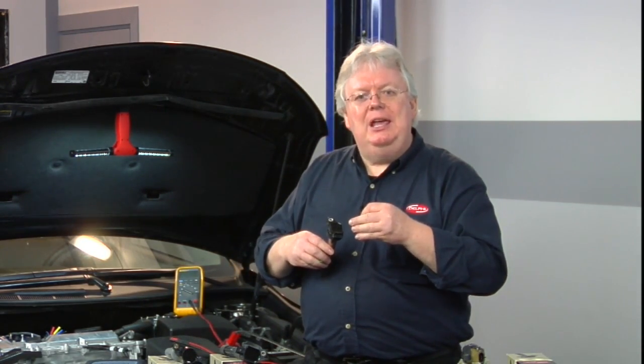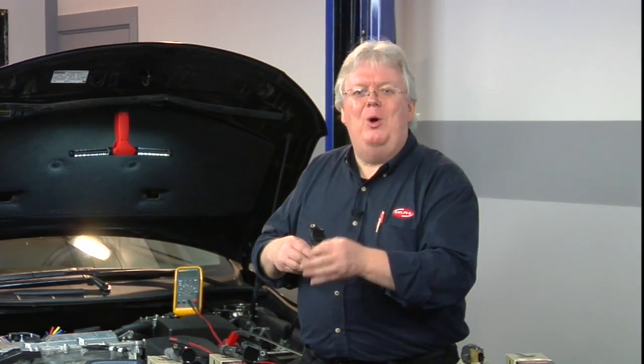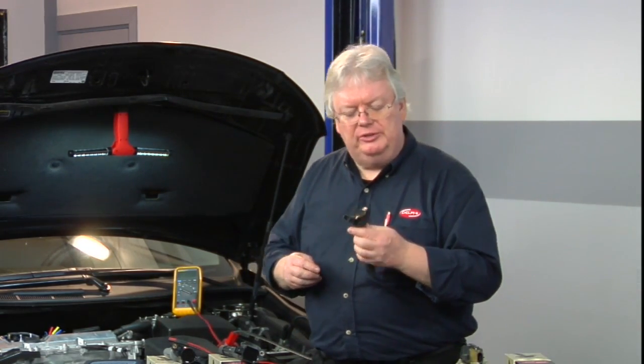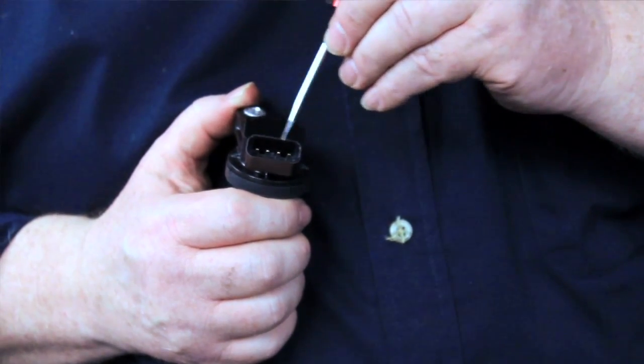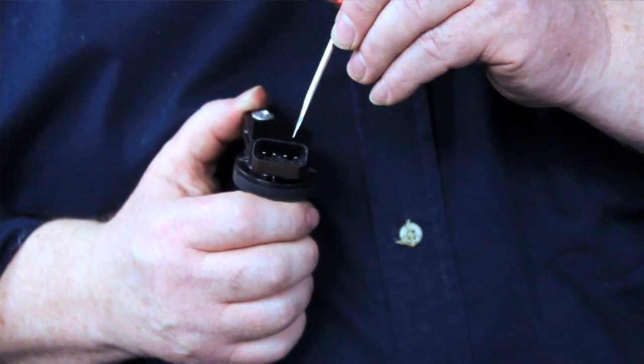So we're not going to be able to really see any kind of a pattern if we had a scope to look into the primary like we would, let's say, with a 2-wire coil-on-plug, like some of the older Fords and Dodge and so forth that have been using for years. The Toyota, the 4 wires are power and ground because it is a module, so we've got to make sure that's good as the first step.